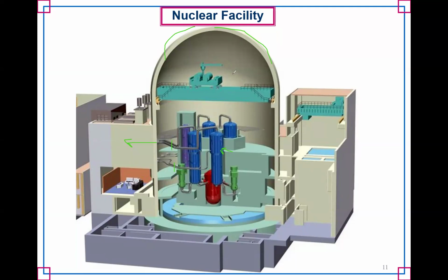They tested it every, I don't know if it was 5 or 10 years. I don't recall quite how much, but they would actually pressurize the containment to 50 psig, and they would verify that it was leaking less than a certain percent, so it would not get damaged. But the containment over here has just an overhead crane because you have to move heavy things in and out. So you use the crane for that.